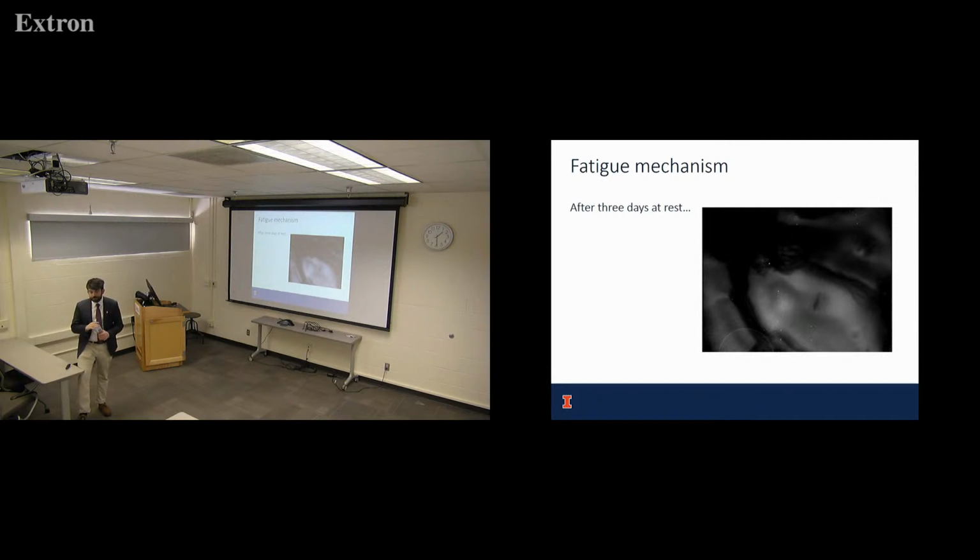About the FEM, the initial part of the presentation, you said you looked at the stresses in the binder, right? The stress in the binder phase, yeah. And you had the strains in the mixture too? So we applied a strain to the mixture as a bulk strain. We had a little cube of mixture that we reconstructed from the CT scans, then applied some strain to the sides of the mixture, basically.